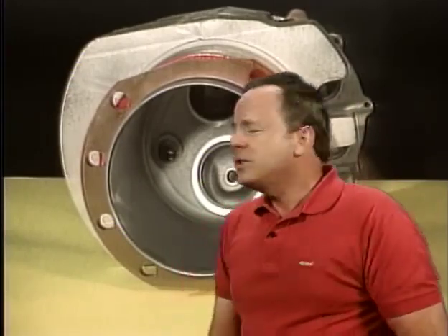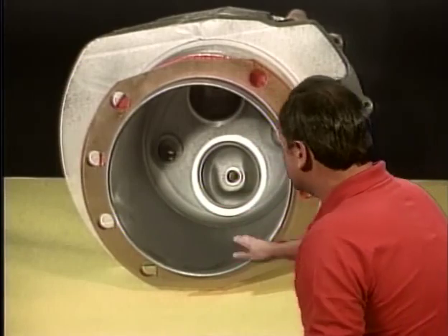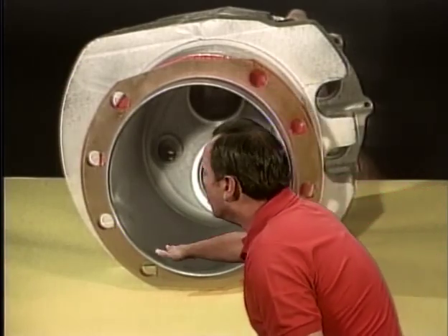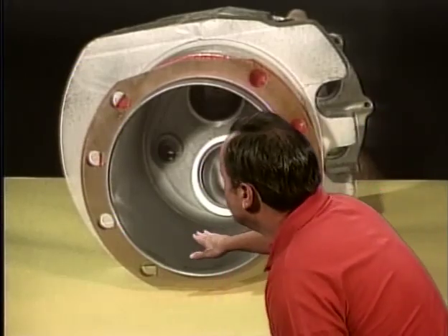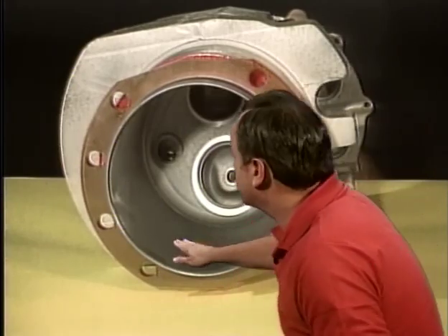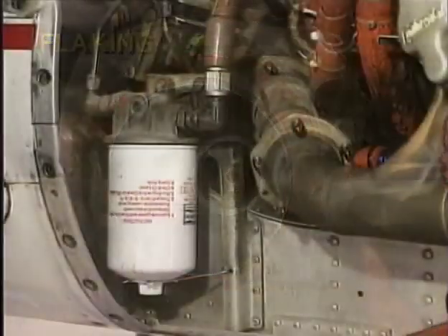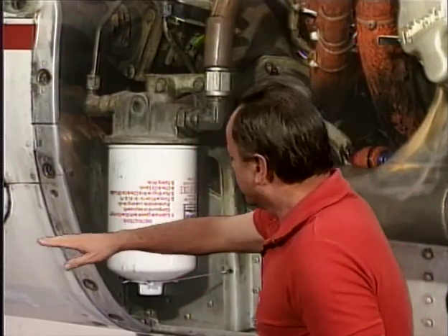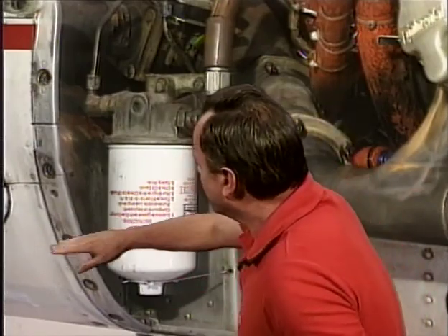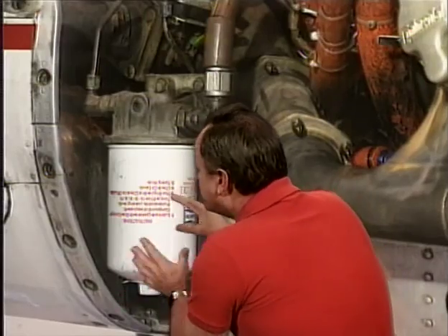How could you get metal particles in the oil screen? Well, one way is you have coated surfaces. For instance, we have a cylinder here. It's coated with chrome. If you have defective plating or excessive loads, metal can flake off. The breaking loose of small pieces of metal from coated surfaces is called flaking, and that flaking could cause particles in the oil screen. Now, as you know, it's always good practice when you're changing an oil filter to take that oil filter apart by sawing it through the middle and inspecting the paper element and see what's in there.